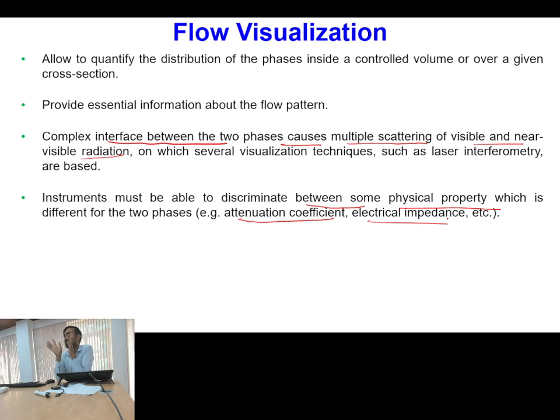Is this point clear? So the overall idea is we have to know the local phase distribution function, because that tells us whether at that particular location we have a liquid or gas. But when we were measuring the void fraction, considering it to be some time averaged quantity, we were just measuring this local phase distribution function at a particular location at a given time.